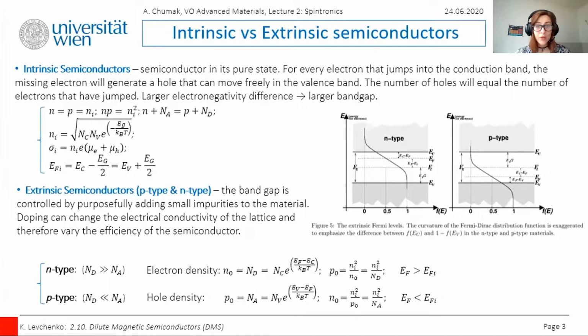Here, I would rather tell you a few quick facts that we should keep in mind while working with semiconductors. So again, the energy model consists of the valence band, the conduction band, and the band gap which separates them. The valence band is a band of electron orbitals that electrons can jump out of, moving to the conduction band when they are excited. So the valence band is, simply put, the outermost electron orbital of an atom of some specific material that electrons can actually occupy, and it is related to the valence electrons.